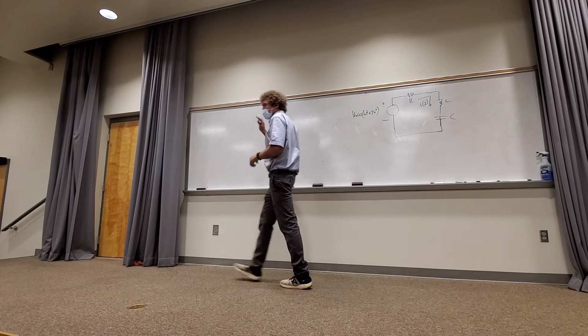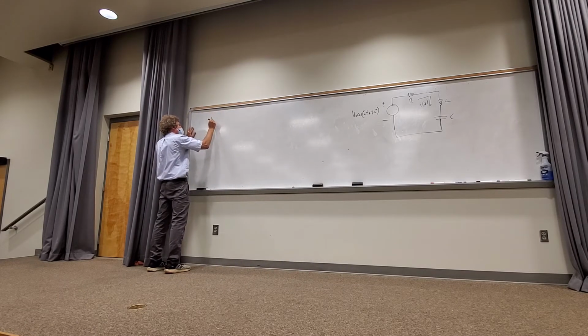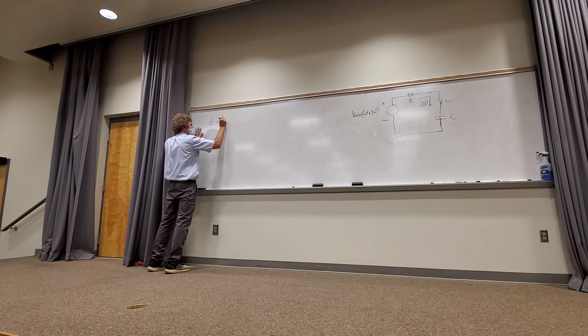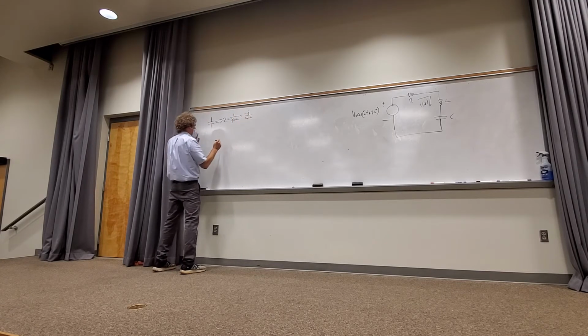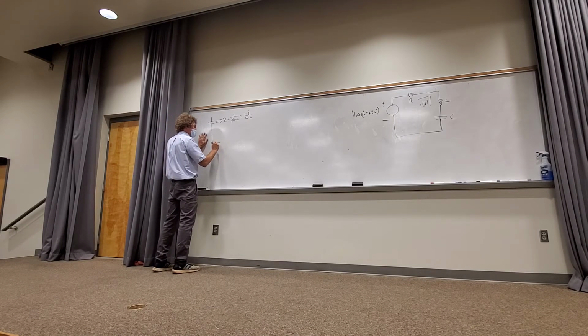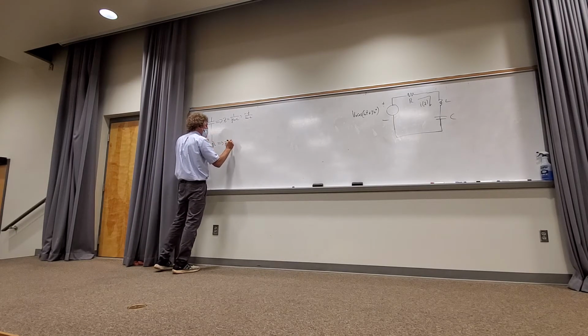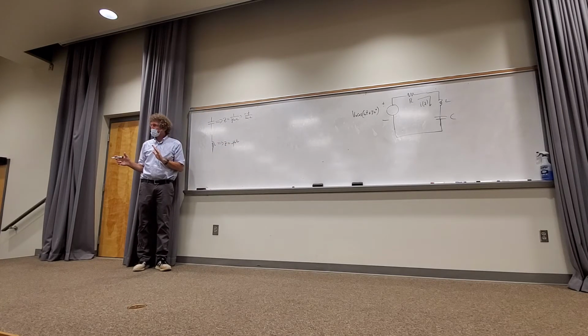And I'm going to put down two things up here. Remember, for a capacitor, this thing has an impedance. Think of it as a complex impedance Z, as 1 over j omega C, or minus j over omega C. And for an inductor, L, this thing has an impedance Z equal to j omega L. All right? Go with me?